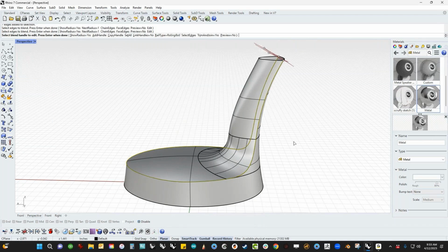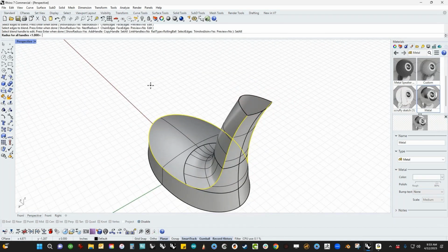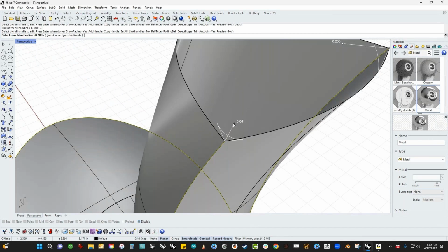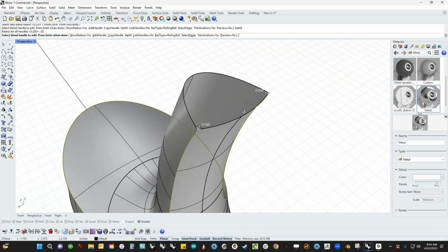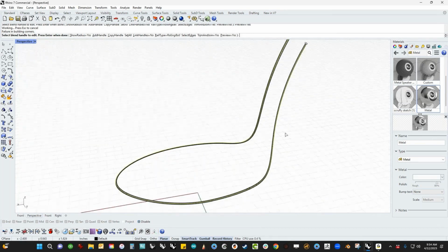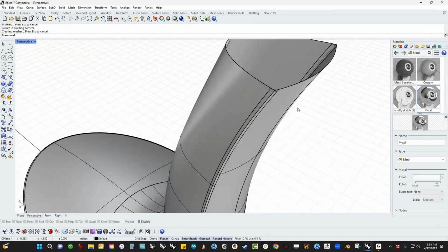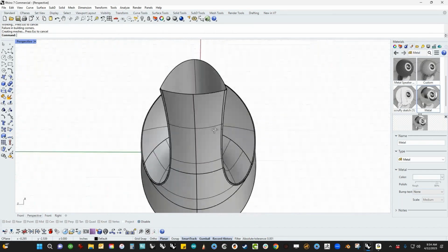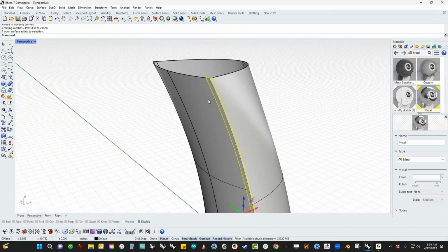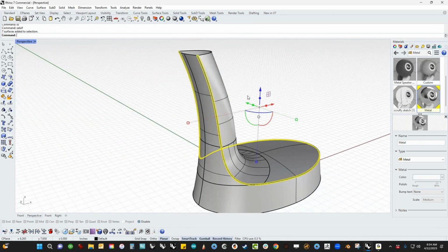And if we try the blend edge command, let's set this to something small, like 0.2. Actually, let's drag a handle and see what feels good. I think something pretty small, like 0.03, I think is what we were looking at. So I'm going to set those all to 0.03. We can preview them, see what it looks like, and then let it roll. And in this case, it didn't make the trim because it either didn't run the surface long enough or whatever the deal was. But we can actually use this as a trimming object, grab these surfaces and join them.